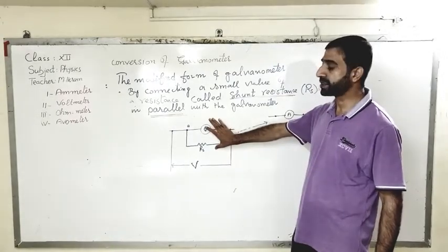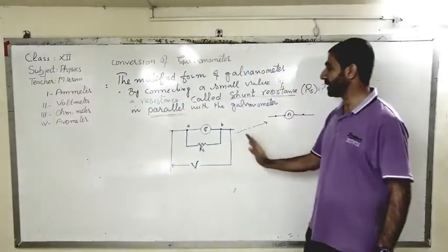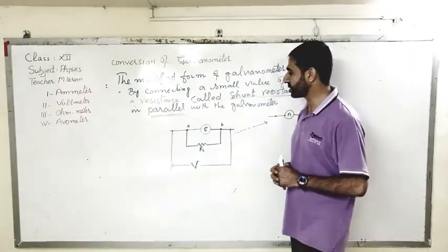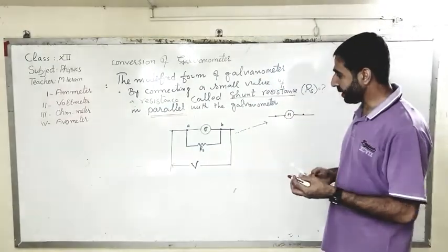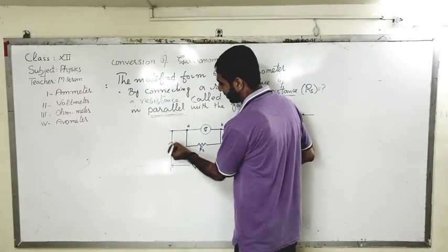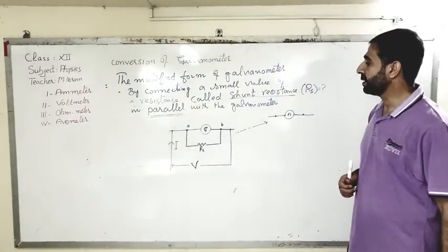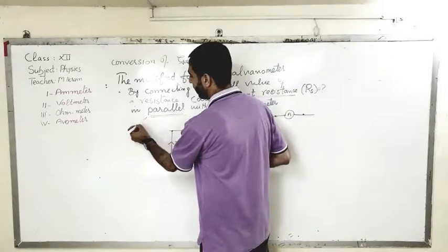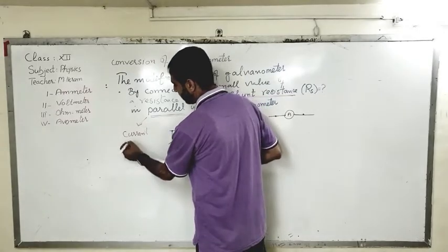This is the construction or the conversion of the galvanometer into the ammeter. It is not that we are using the ammeter, so you should make a difference between these two statements, right? Now let us label this, that the source current is I. Clear? Now you know that parallel circuit is a current divider. Parallel circuit is what? It is the current divider circuit.